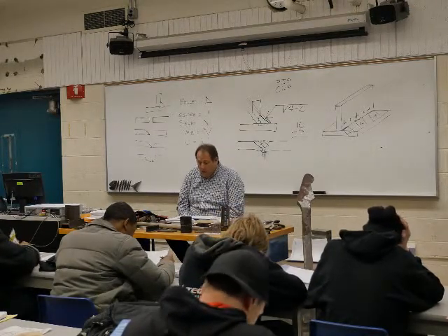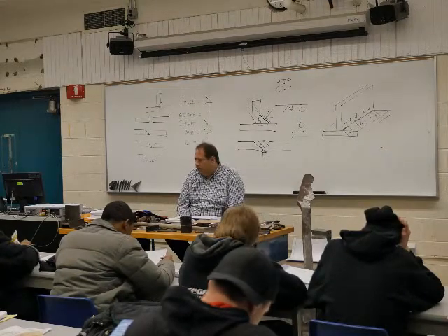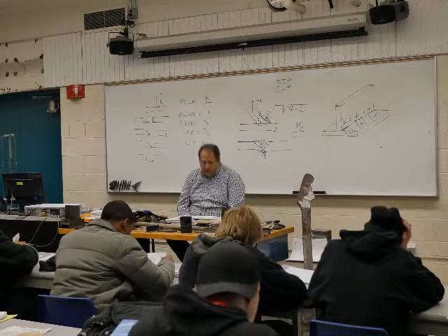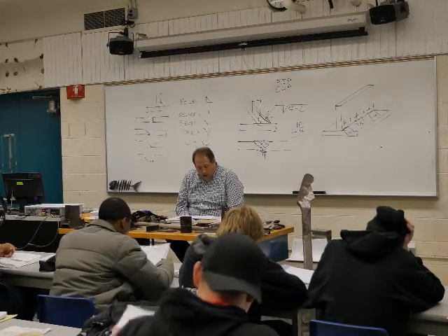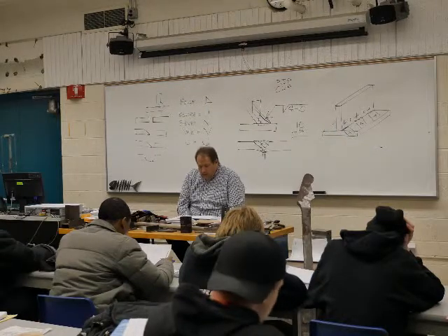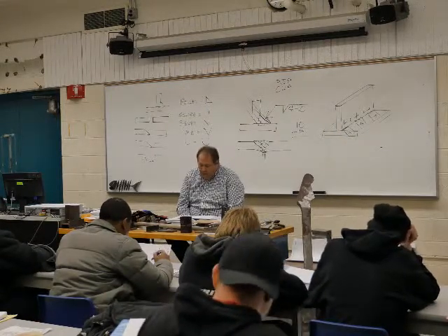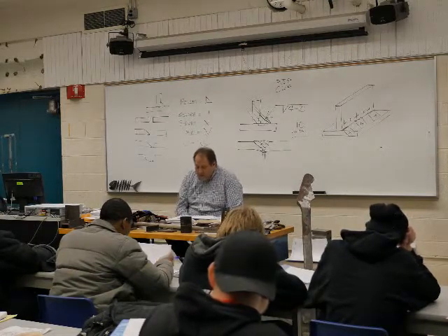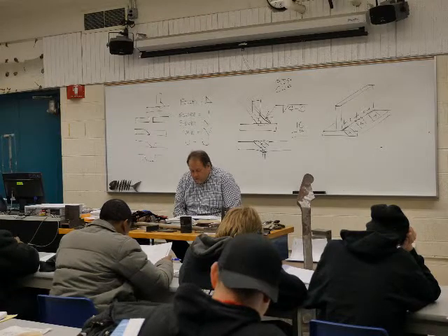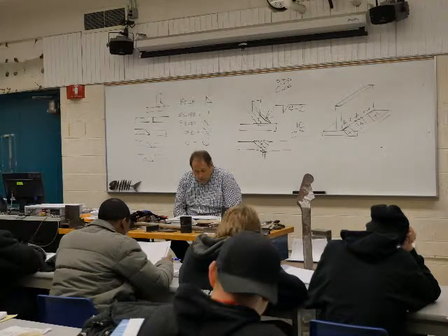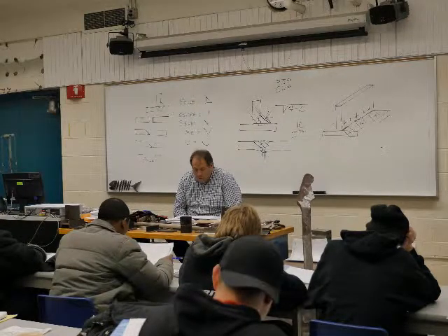Also look around the print itself for notes, because you may have something. This one not necessarily. We have 3 different views, labeled view X, view Y, and view Z. Let's start with this. Just count how many weld symbols you see in this print.